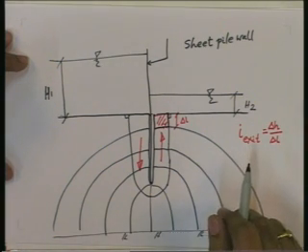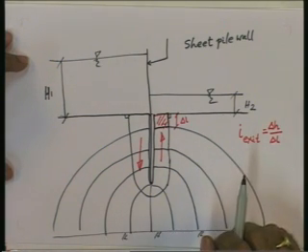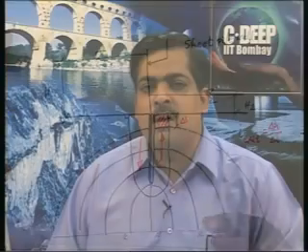Then we also discussed the critical hydraulic gradient, while discussing the flow of water through soils, where we defined that when the head reaches the critical head by the length of that flow, that is treated as the critical hydraulic gradient, and it can be related as (Gs minus 1) by (1 plus e), which equals gamma dash by gamma W.